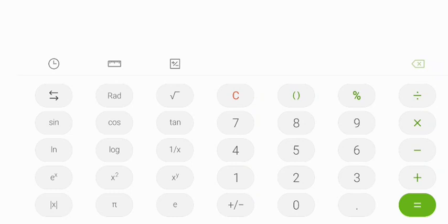When we put those values, 6 into 180, we get 1080 divided by 72. So the answer is 15. So y, the angular slot pitch, is equal to 15.